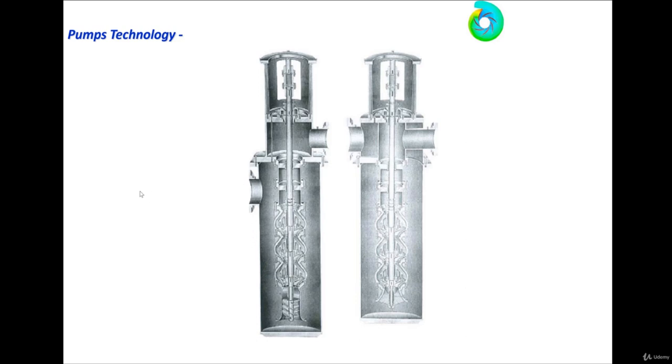So you fill this can, the vertical can, this is the external can, with the liquid, and you have sufficient net positive suction head available with respect to the first stage impeller. The first stage impeller can use this NPSH to pull the flow and move it through the shaft and out of the discharge nozzle. This is the outer can, and this is the head.